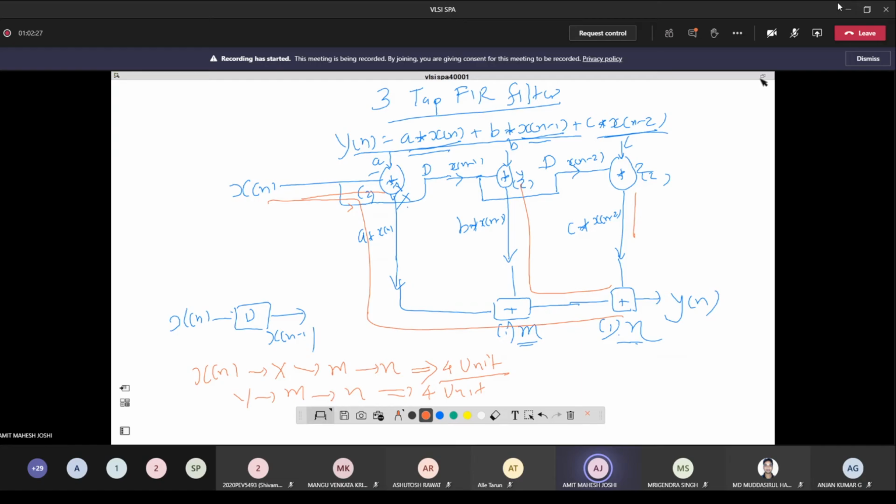Actually, this problem is slightly simple. Why is it simple? How many loops do you have? Zero. There is no loop. So if there is zero loop, then one property for retiming we can just ignore now: the number of delay elements inside the loop remains the same.